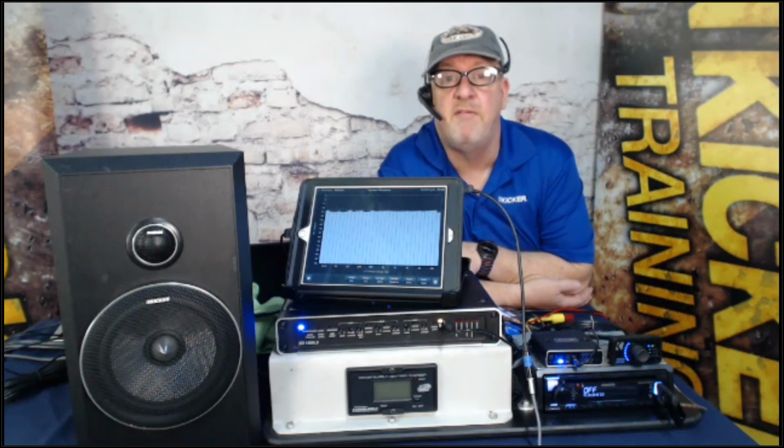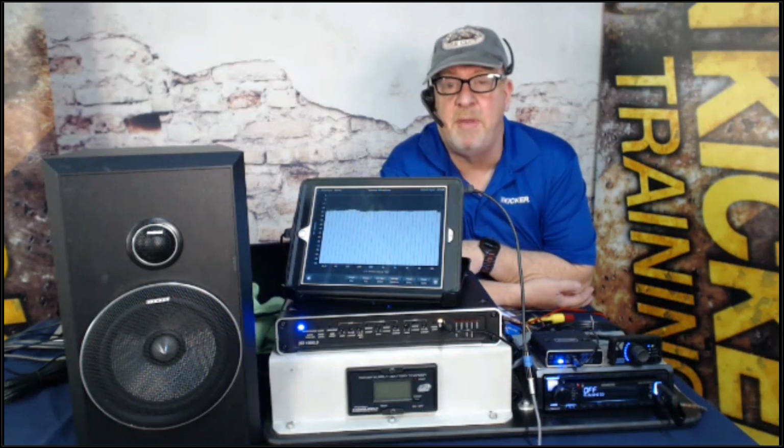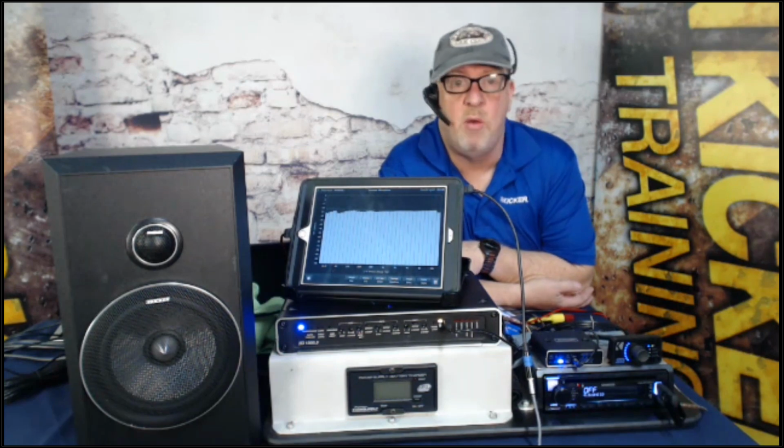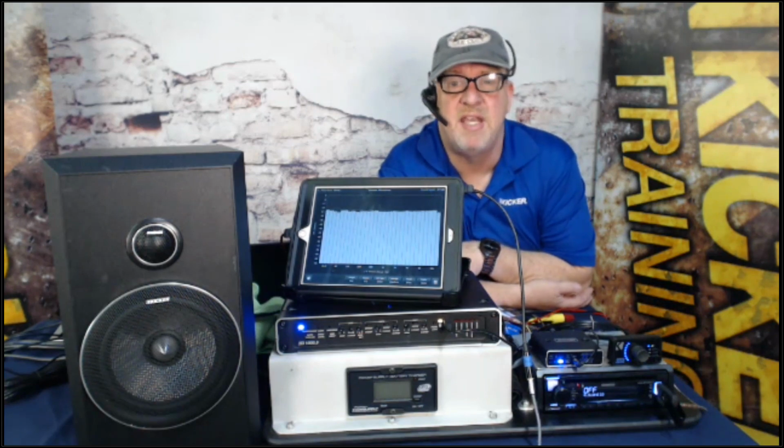Actually, the very, very near future, because that's going to be a piece that'll compensate for that bass roll-off. It's fully active, and it works out absolutely incredible. For the meantime, if you have a system that has roll-off and you're wondering how to set the gains, turn the volume of the factory radio up to the point where the bass starts to roll off, stop at that point, and that's where you set the gains on the amplifier to reach maximum output. And we'll cover that in the session when we actually show you an oscilloscope and show you how to measure clipping with an oscilloscope and an RTA.